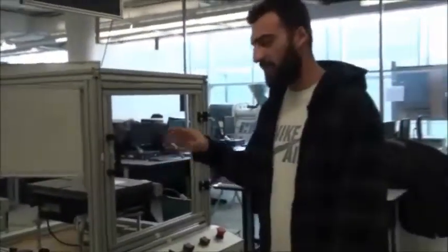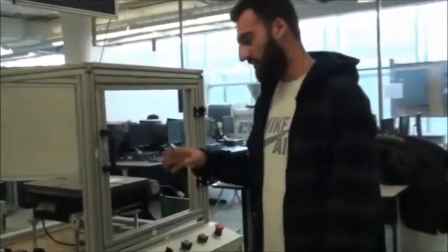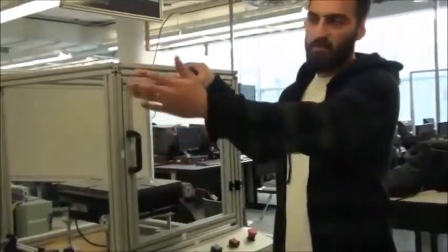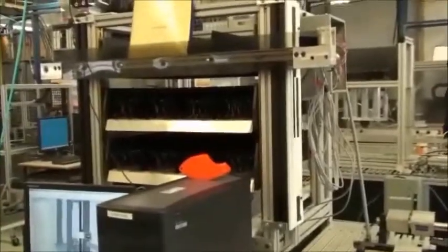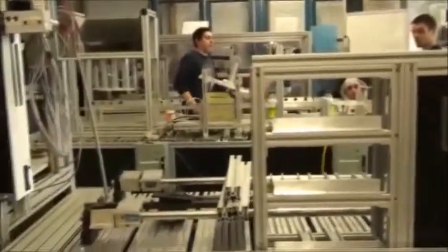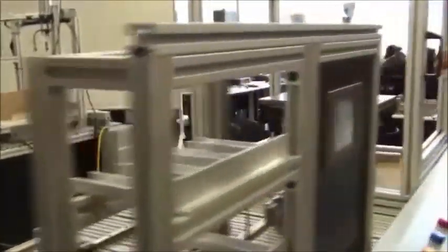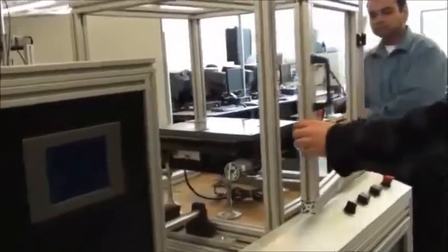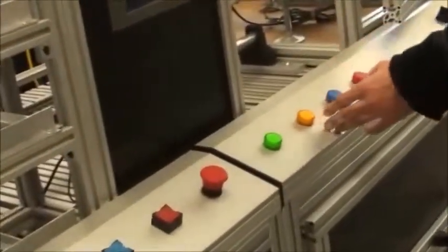The safety aspect of here includes mechanical, electrical, all that good stuff. What it does is it picks up the component from the bending machine, and it brings it over on the sliding table to what they designed, brings it over to the clamping mechanism, and at this point the operator is really needed, right? What the operator does, if this machine is currently in motion, this green piece lights up, telling the machine that this is a new part.